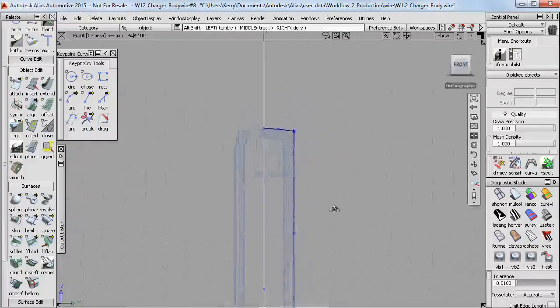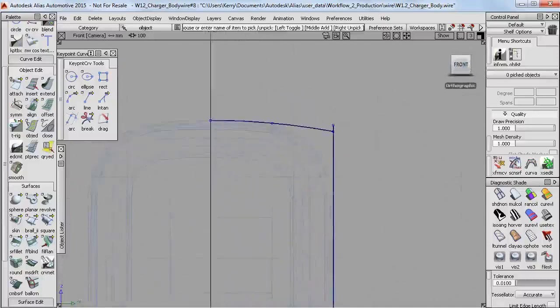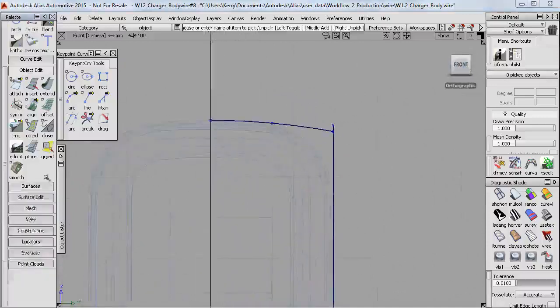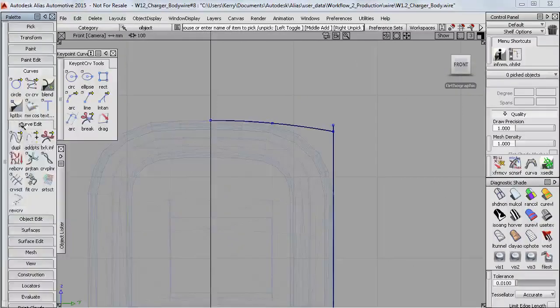And then up here at the top, I've got this large fillet. It's a decision I have to make whether to do this as a curve now or as a surface fillet later. But I'm just going to do a curve fillet. And it's going to default to 100, which is a bit big. So I'll just try 90, which, yeah, that looks a bit better.